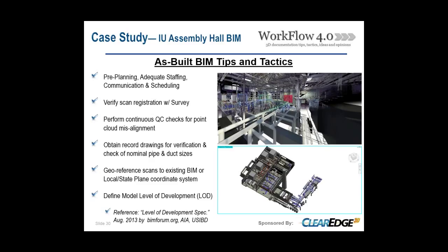And again, we're finding with the Edgewise tool, we can perform continuous QC checks in the model as we go along. Although we're laser scanning and we're not relying on them a whole lot, we still like to get our hands on the record drawings to at least verify nominal pipe and duct sizes. We believe that's a helpful tool in doing that.